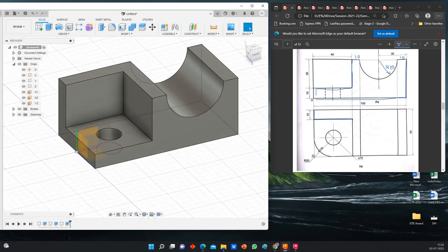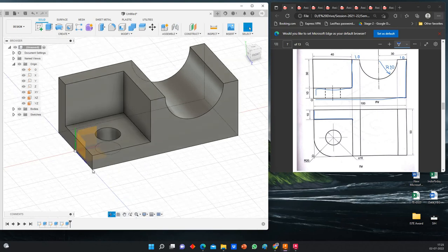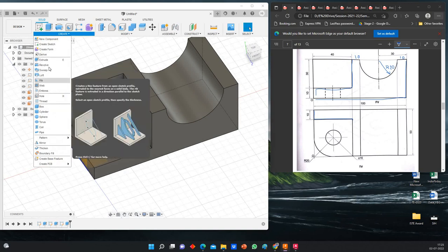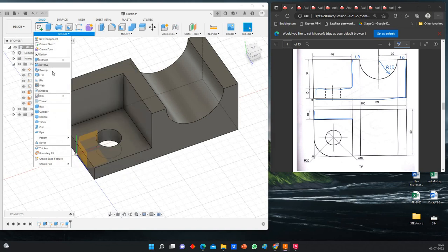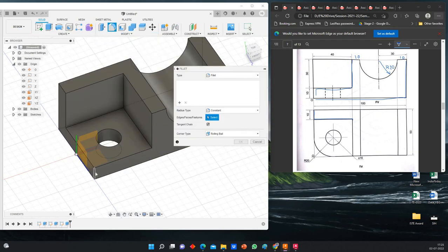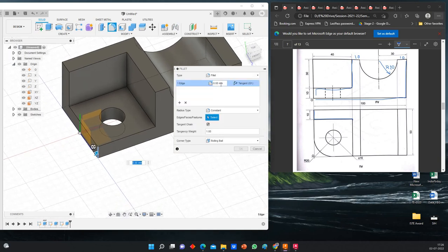So this part here, this is a fillet. So for that we have to use the 4 center method in the regular method. Now I have to use the fillet command. So I will select this line here, only this line. See the fillet command, and now what is the radius here? 20.